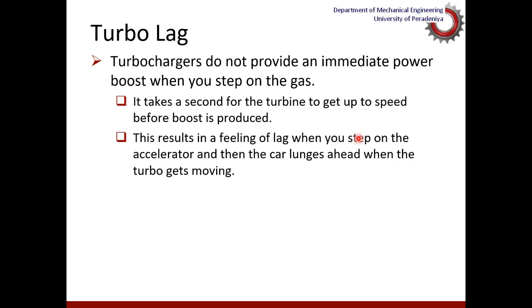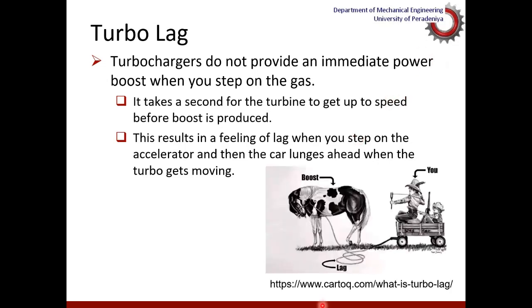So the driver presses the accelerator pedal and requests more and more power to be produced. But if the turbocharger could not respond that quickly, then there is a delay in accommodating the driver's request. So in simple terms, this is a diagram downloaded from the web. So this diagram clearly shows what this turbo lag is.